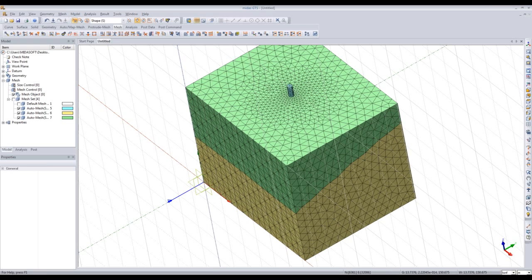Okay, but that's a big issue for us here. So we either embed or do the boolean cut and then mesh. That's correct. Yeah. Sorry, I skipped over that point. I didn't realize it was that critical for you guys. But yes, you're right. You'd follow that process in order to keep the meshing continuous.